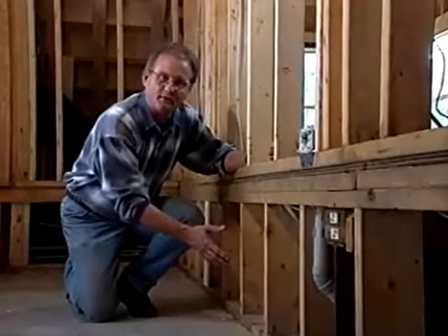but they're wrong. That's right. Insulation is not an air barrier. It slows the movement of heat, but it does not stop the flow of air. Watch what happens when smoke is blown through a piece of insulation. You can see the air moves easily through it.